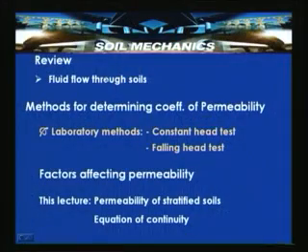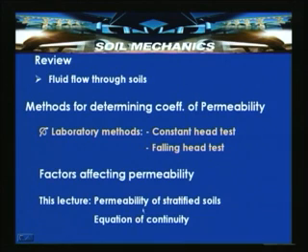So, the review, like the previous classes, we have started fluid flow through soils, and then we have also discussed methods for determining the coefficient of permeability of soils. Then we said that there are two methods, one is constant head permeameter test, the other one is falling head permeameter test, which are there in the laboratory, and we discussed the merits and demerits of each method and their suitability to a particular type of soils. In this lecture, as informed earlier, we will be looking at permeability of stratified soils and equation of continuity.